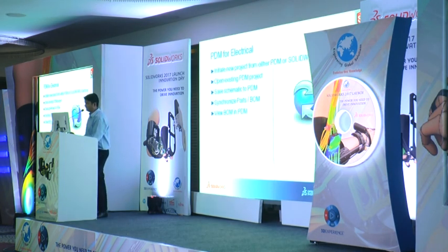And it can easily integrate with data management tools like PDM. The user doesn't have to create a new project in the SolidWorks tool each time. They can create projects in the PDM tool also, and assign permissions based on who is going to work on this data. They can also generate the BOM in this. Finally, I conclude my SolidWorks Electrical.